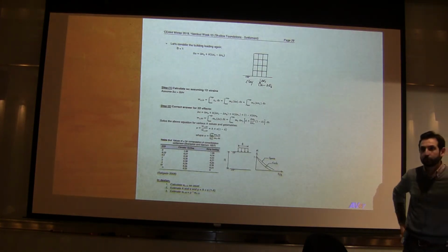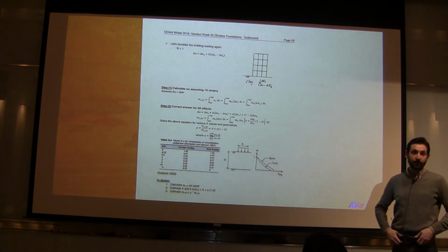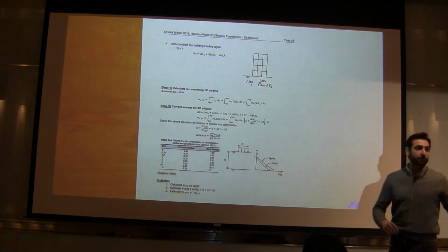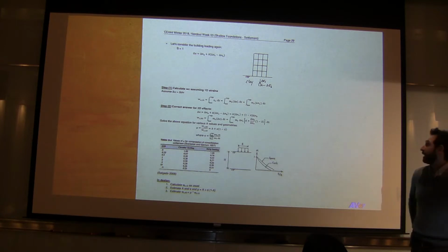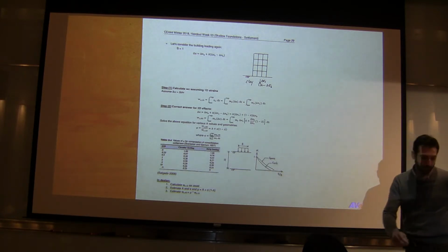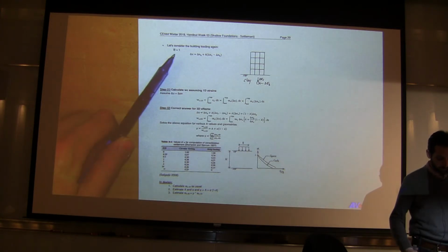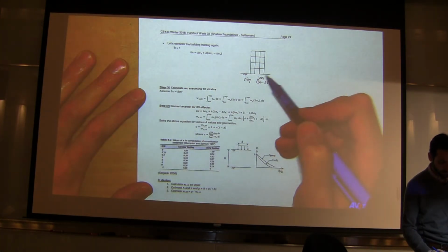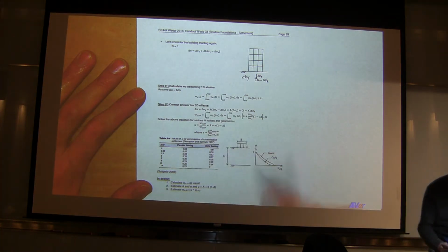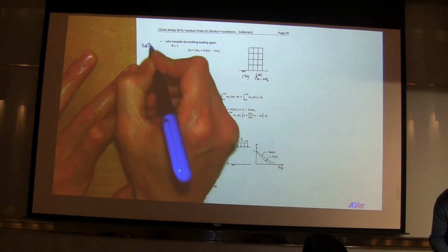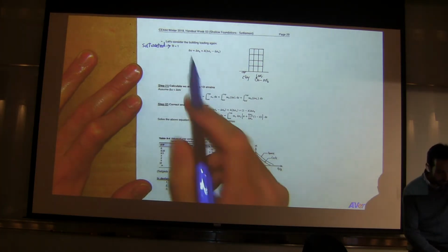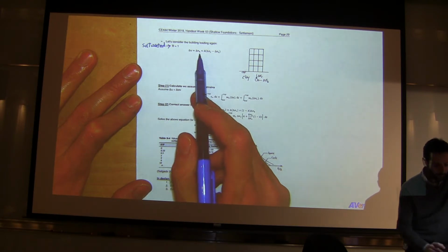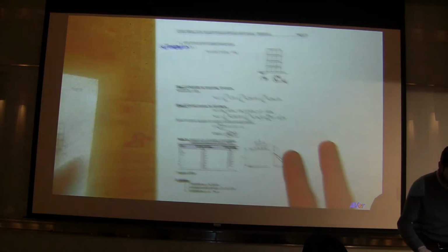So now let's go back to the actual building analogy. The Skempton equation was developed for a triaxial test. Now, in a real-world situation, we can just assume that B is 1. That's your building sitting on clay. It's saturated, so I'm just going to assume B is 1. Therefore, your delta U becomes, and I'm going to put the equations side by side.